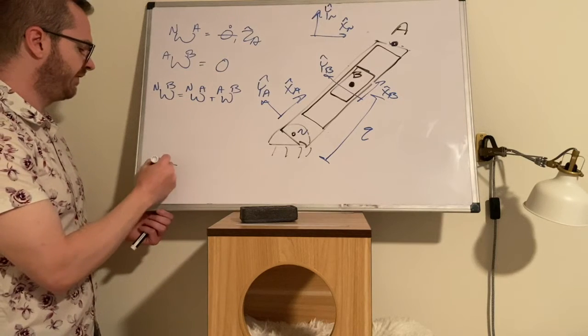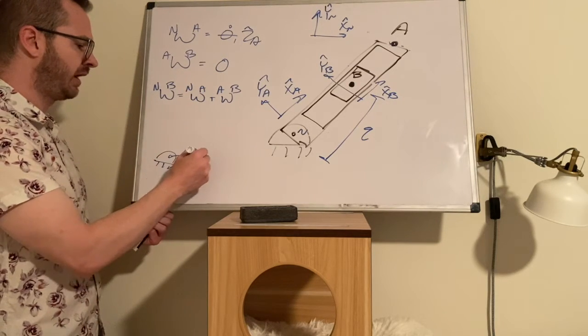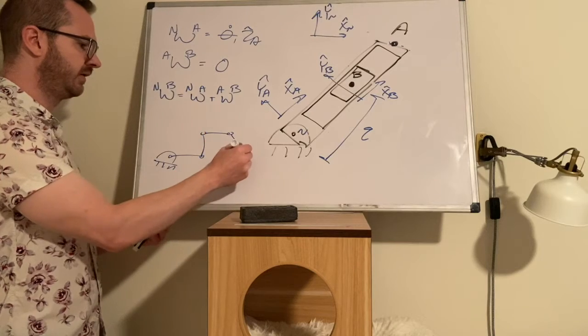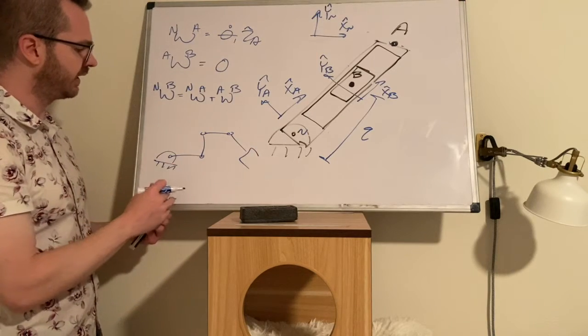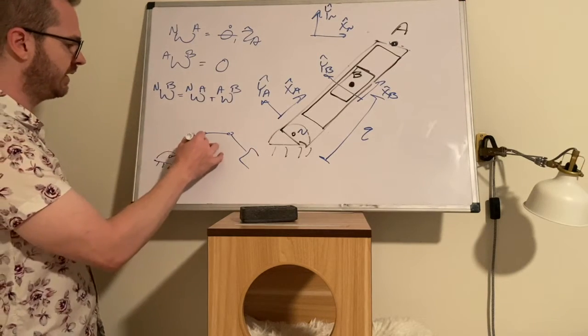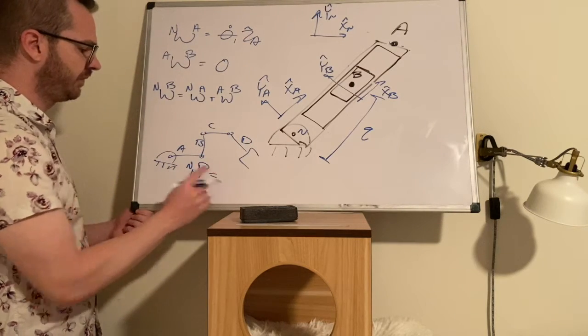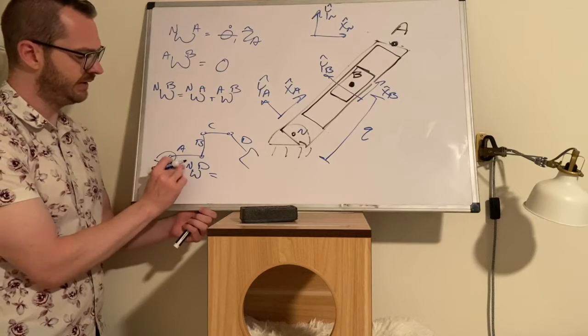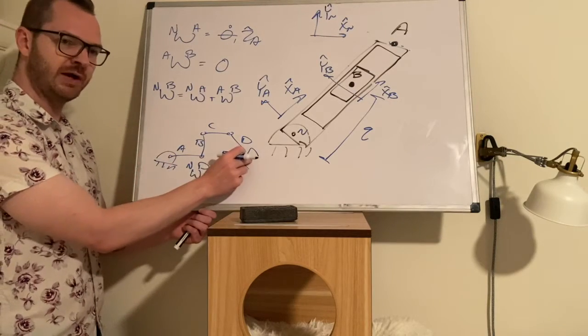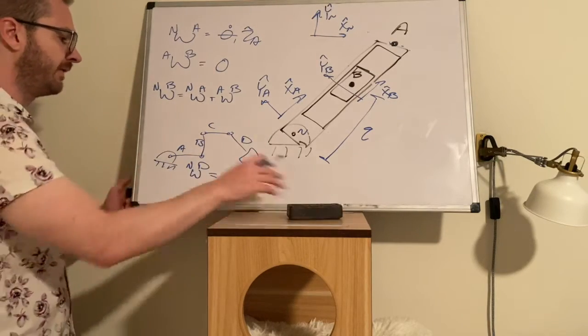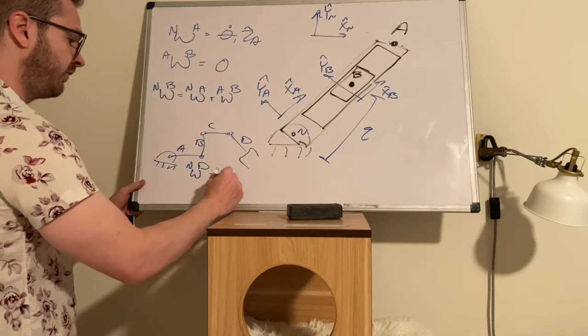So if you have a case like a robot with all of these lengths, and they're all spinning and doing all kinds of stuff, A, B, C, so here's D. If we want the total angular velocity from N to D, base frame all the way down to this wrist frame, then really we just have to find it for the individual parts.